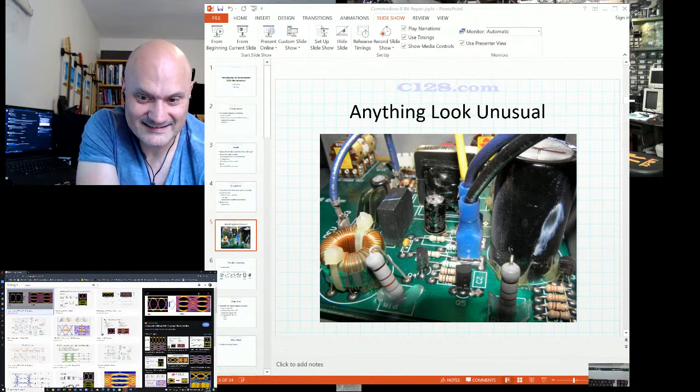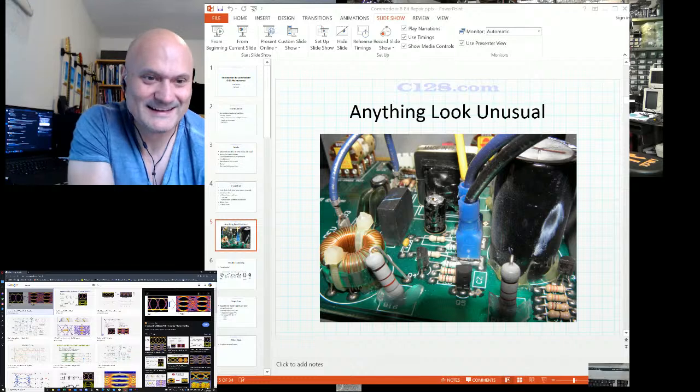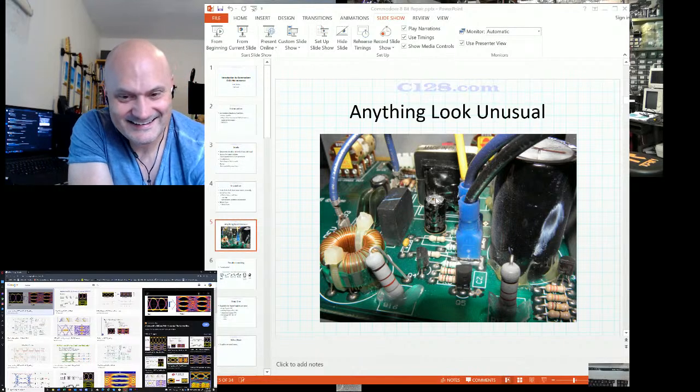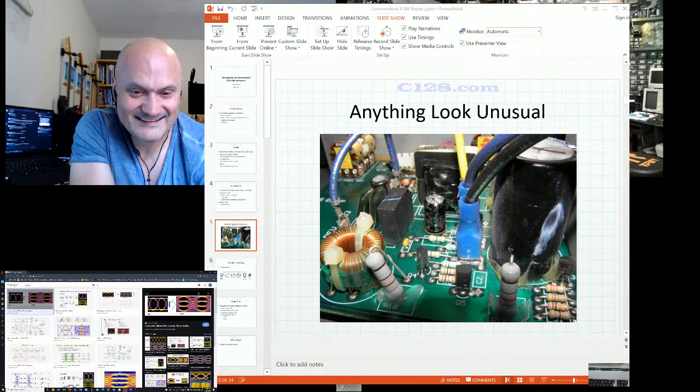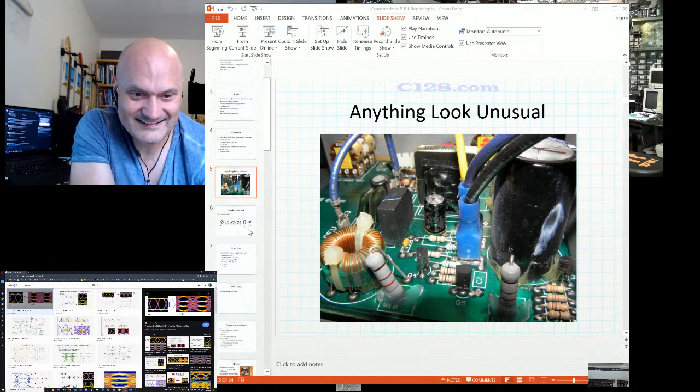And here in this set, I don't expect people to be able to see it, but there is something unusual here, and that is if you look right here, capacitor. The capacitor is domed. If it hasn't blown, it's about to. I think there's a little dot of stuff, so it probably has blown here. Yeah, it's actually leaked down the side here a bit. So that's your very first thing with troubleshooting, in my world, is use your eyes. Take that 5-10 minutes to look at everything that's in there.